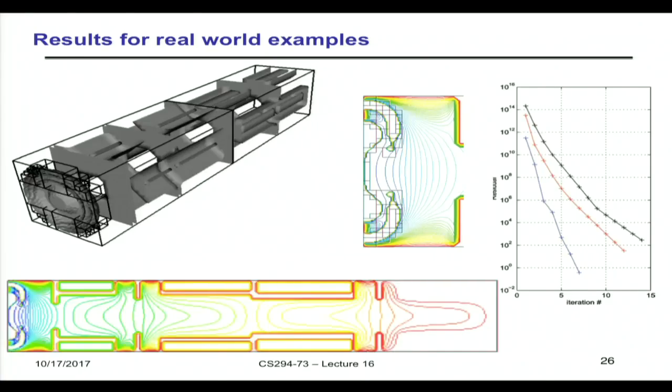You've got to solve the whole thing with these geometry cutouts and other things on it. And this is the multigrid convergence. So for a given iteration, this is how much it reduces the residual. So from 10 to the 14th up here all the way down to 10 to the 0, which is about as much as you're going to get with a double precision round-off sensitive algorithm.